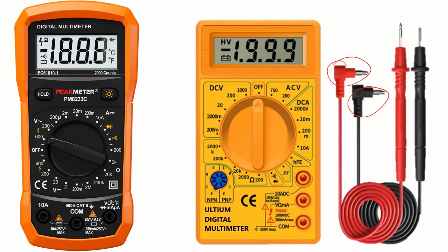Now we are going to observe this little icon which resembles a speaker. Turn this head so that it points here. Take the two terminals, already connected to your ports, and join them together. It is going to produce a sound, which means the multimeter is functional. Is that okay? So always test for continuity first before you start using your multimeter.